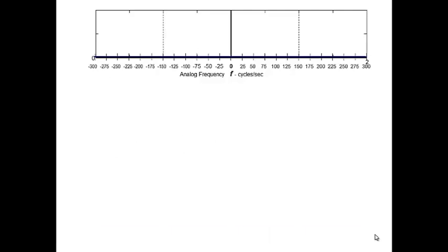So today what we want to do is pick up on the topic of aliasing again that we worked through last time. At the end of Monday we heard aliasing, we saw where it comes from, the sampling process, and we took a simple example of a single frequency sinusoidal signal and used that to study how we can predict where in the frequency spectrum, if the signal aliases, where does it go?